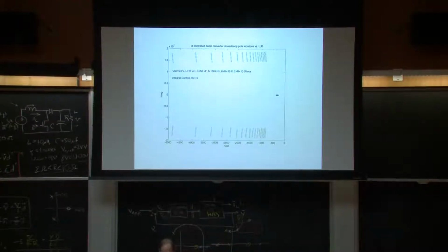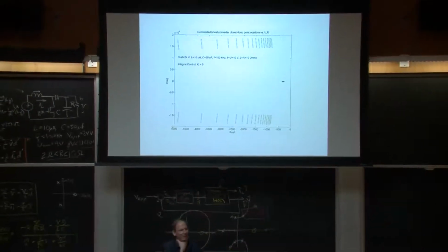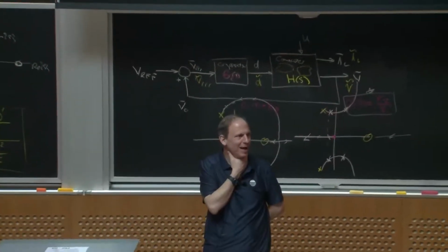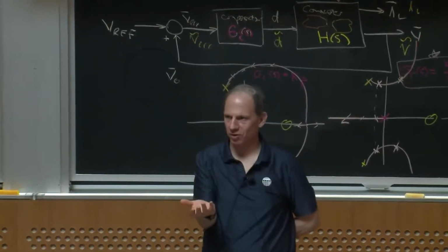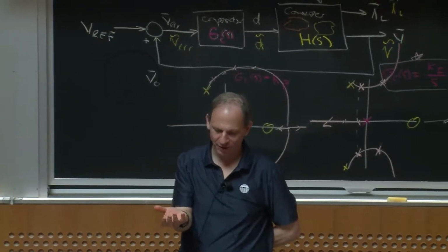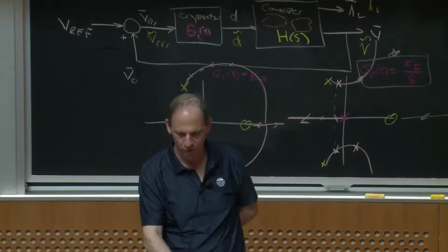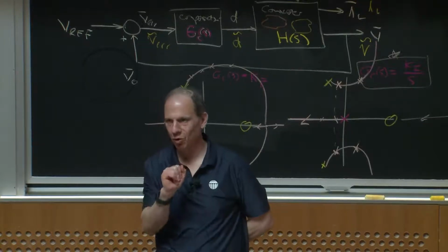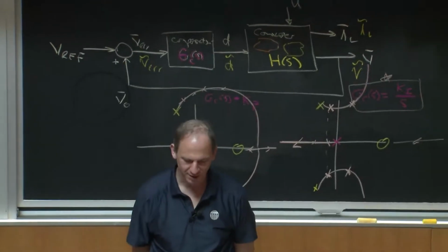Okay, how stable is it? And this is where me and your average control textbook break paths in terms of what we're happy with, okay? A typical measure for those who do control are things that are either like the phase margin you have or the gain margin you have on your loop, right? So what you do is you look at the loop gain and you plot that out, and you can look at the open loop gain with a controller. This is what it looks like.